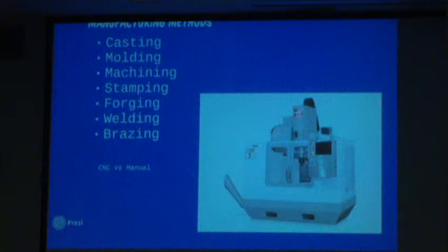And then you melt the wax out, and you pour molten metal into the ceramic. Then you cool the metal in that shape, and then you crack the ceramic off, and now you've got a metal part in that shape that you desired. Okay? So it's lots of steps to get there, but once you do that, you can make a whole bunch of those waxes, which gives you a whole bunch of the castings, so you can make those metal parts quickly.